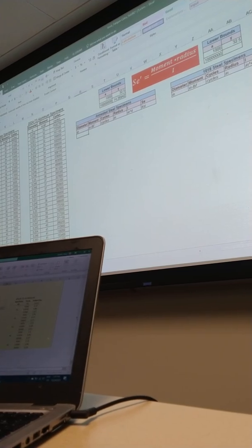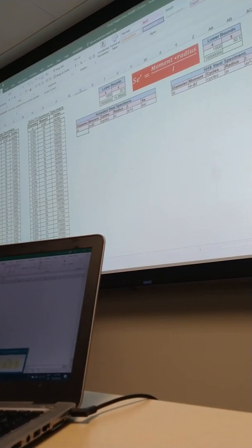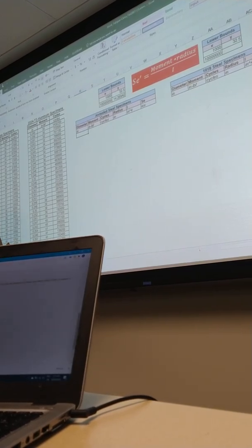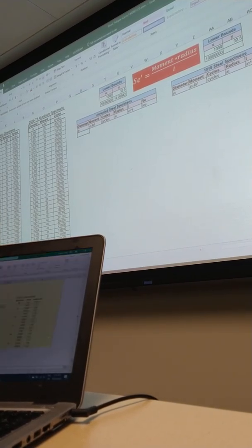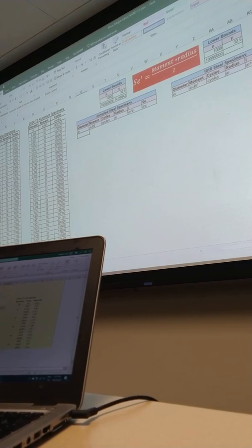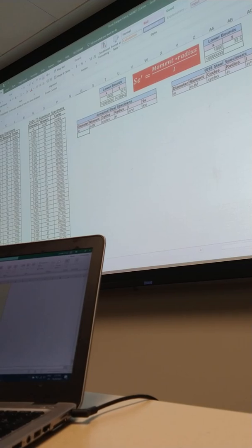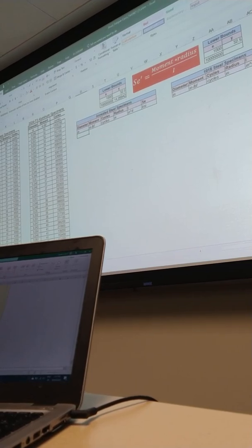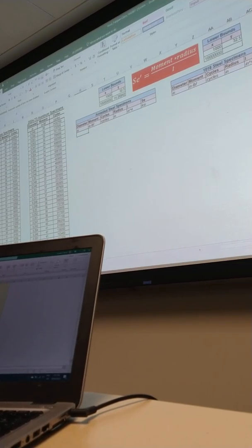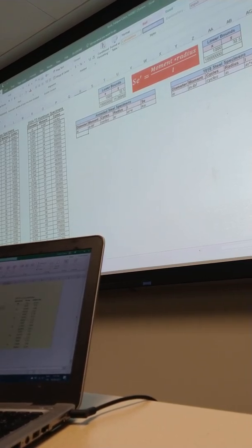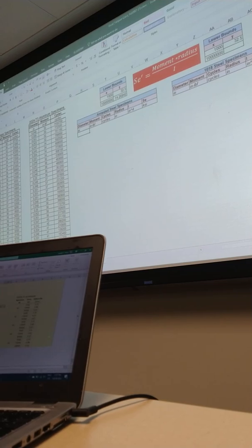So really quick, I believe the video I showed you guys last time was they had an axial apparatus. It applied axial loading to the specimen. So tension, compression over and over again for hundreds of thousands of cycles. There's another way to do it, where you use moment. So you apply a moment and then you can back calculate the stress cycles, the axial stress in that moment. So that's the way we're going to do it.